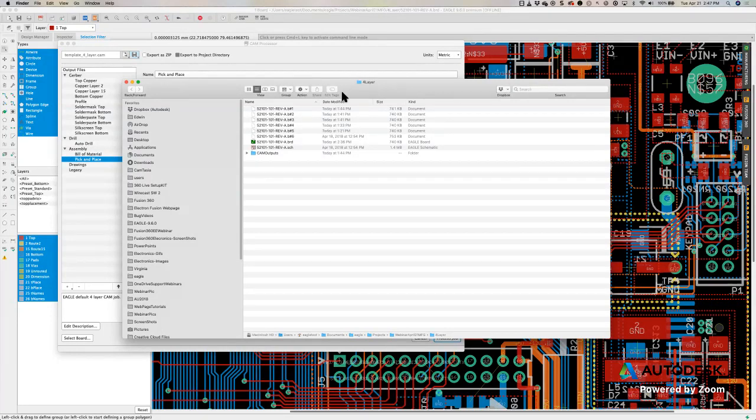Okay, very well. So all the files, as you could see, these were my board and my schematic files. Just to let you know, these $1, $2 files, every time you save, these are backup files. So it's constantly doing backup files. It does up to number 9, and then it comes back and keeps on doing it all over again. If you ever need to recover, you just rename one of these files and look at the timestamps. That way you know which one you want to recover from.